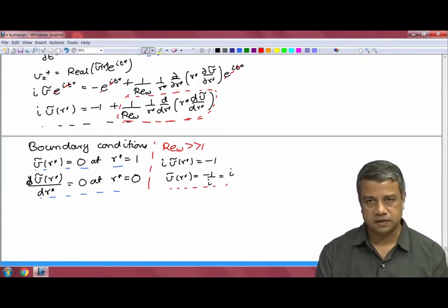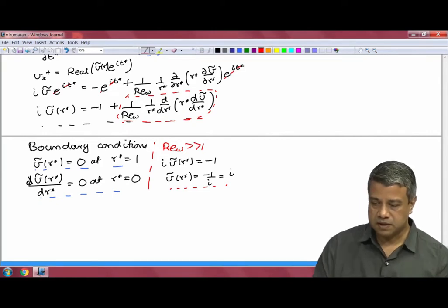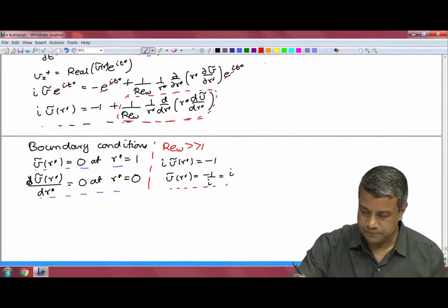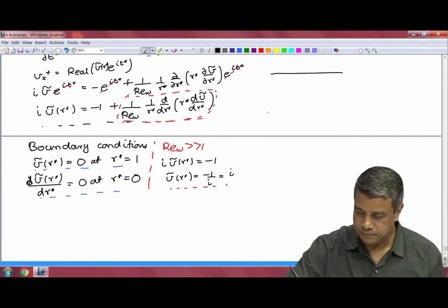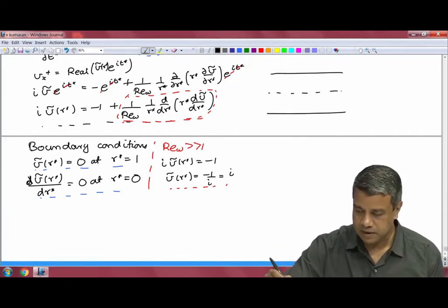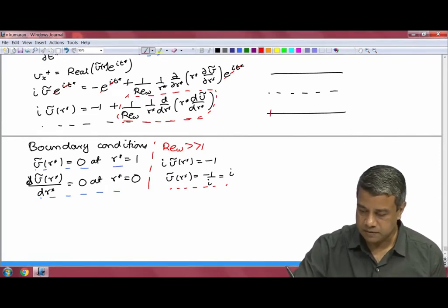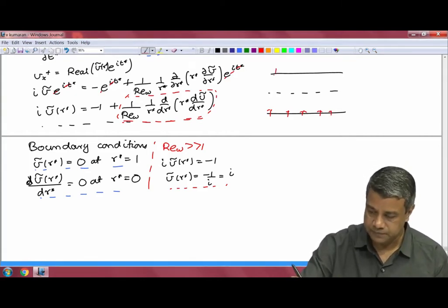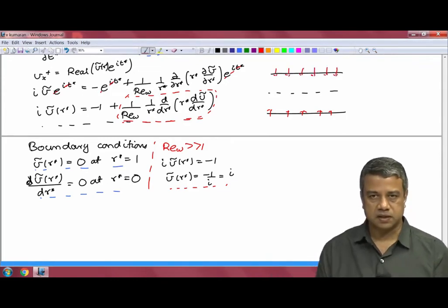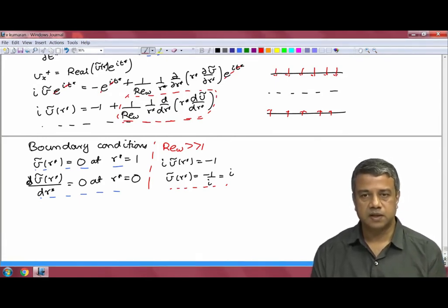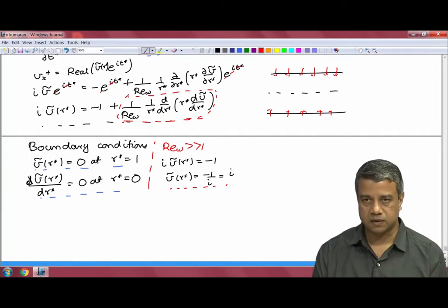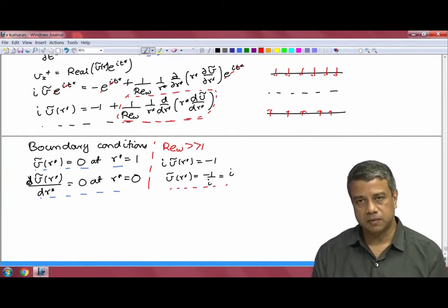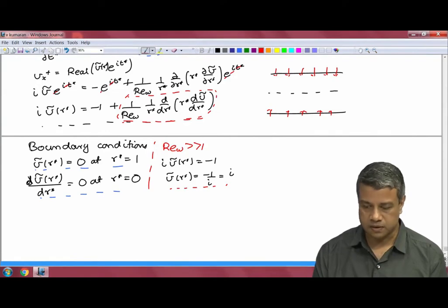This is however unphysical, because if you consider the flow close to the wall, there is a balance between momentum diffusion from the wall, and the velocity that goes in the positive and negative direction, which convects the momentum along the wall. Even if the Reynolds number is large, there will be momentum diffusion, but that will be restricted to a thin region close to the wall.